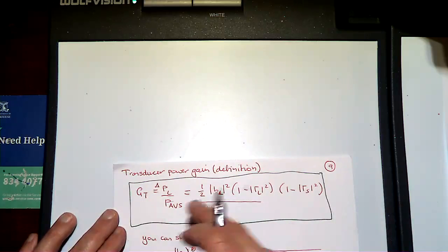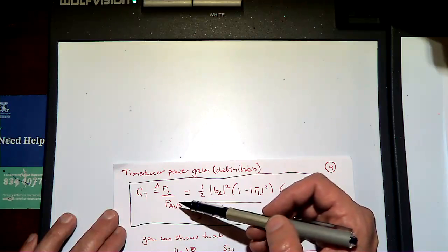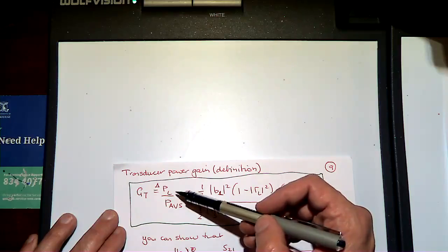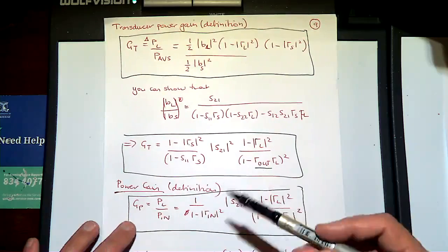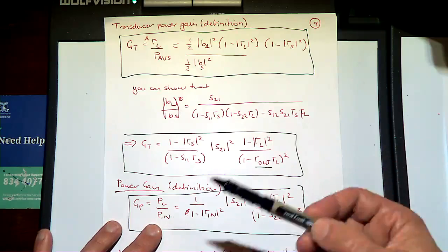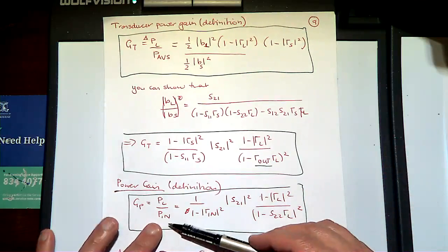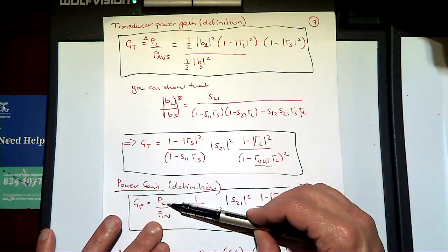Okay, so here what we're saying is, what's the best I can do for the particular generator that I have available, in order to transfer power to the specific load that I have. Here, what I'm saying is, given I've got a fixed input impedance or input power to my system, what's the maximum power I can deliver to the load, right?